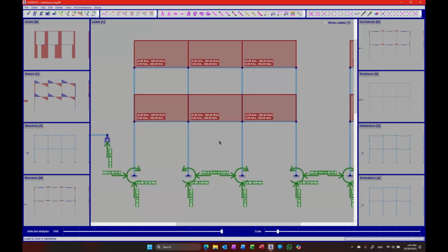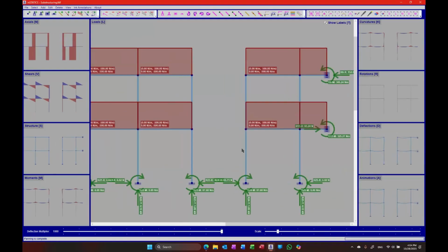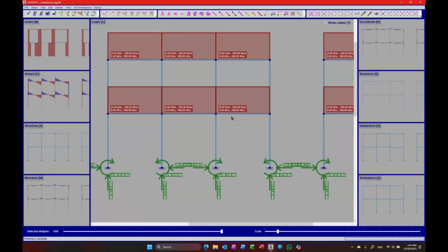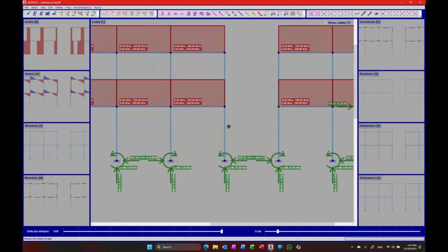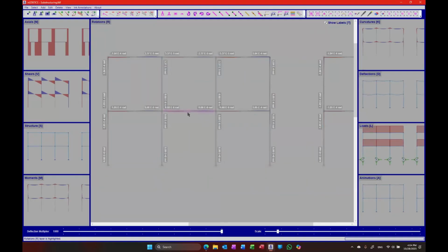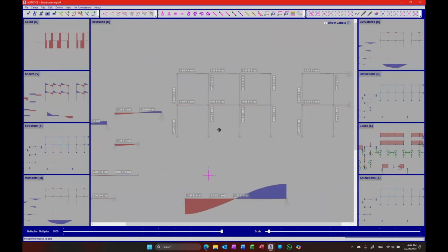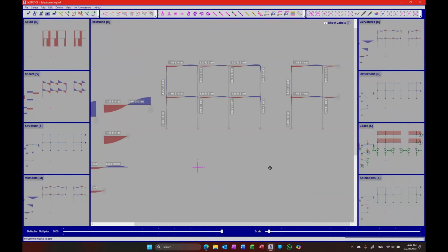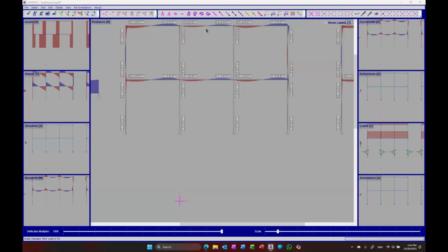And imagine this was a very, very large structure, right? If it was very, very large and our computer was not powerful, we might consider creating a condition where we say, okay, well, the structure is symmetrical, the loading conditions are symmetrical. Why don't I cut it right here in the middle and apply the same trick, right? Don't allow rotations, because why? Because I know that the rotations, well, who's rotating all this much? Oh, these guys. Let me just delete this for a second, just to be able to see the rotations here. See, the rotations in the middle are 0.